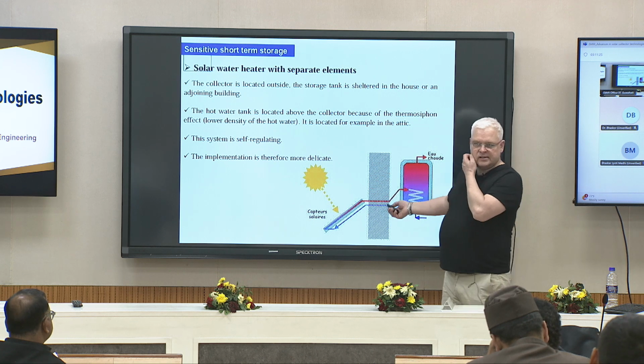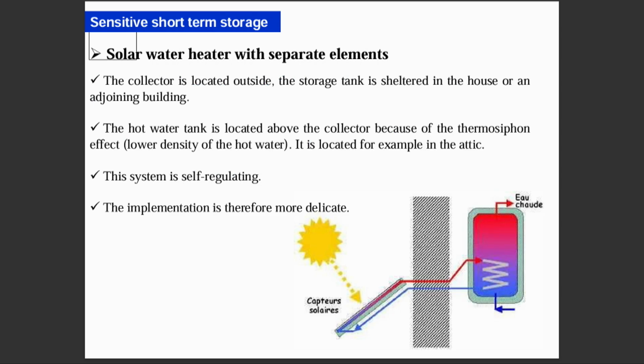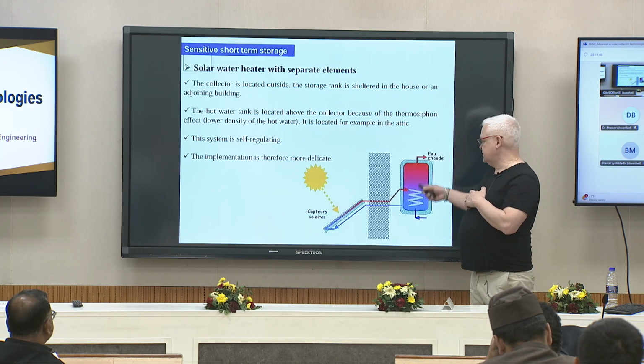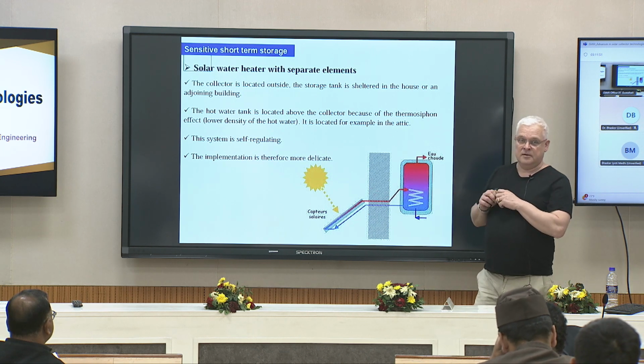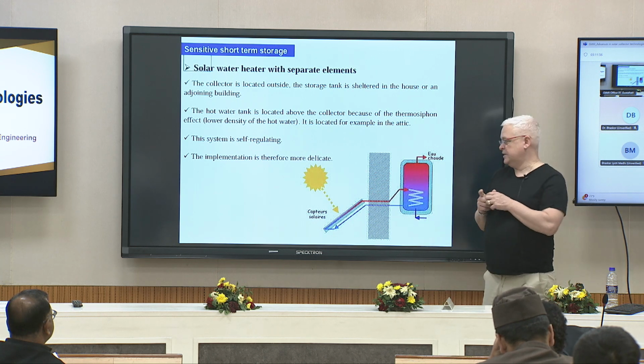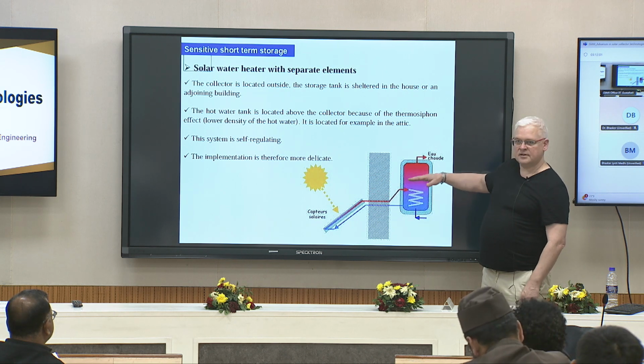We have more of this with an external flat plate collector and a thermal storage tank which is inside, in order to avoid giving too much heat to the environment. The other advantage is the orientation. Here it is horizontal; this is vertical, and it is the main efficiency parameter of solar thermal storage, because in this configuration you have thermal stratification.